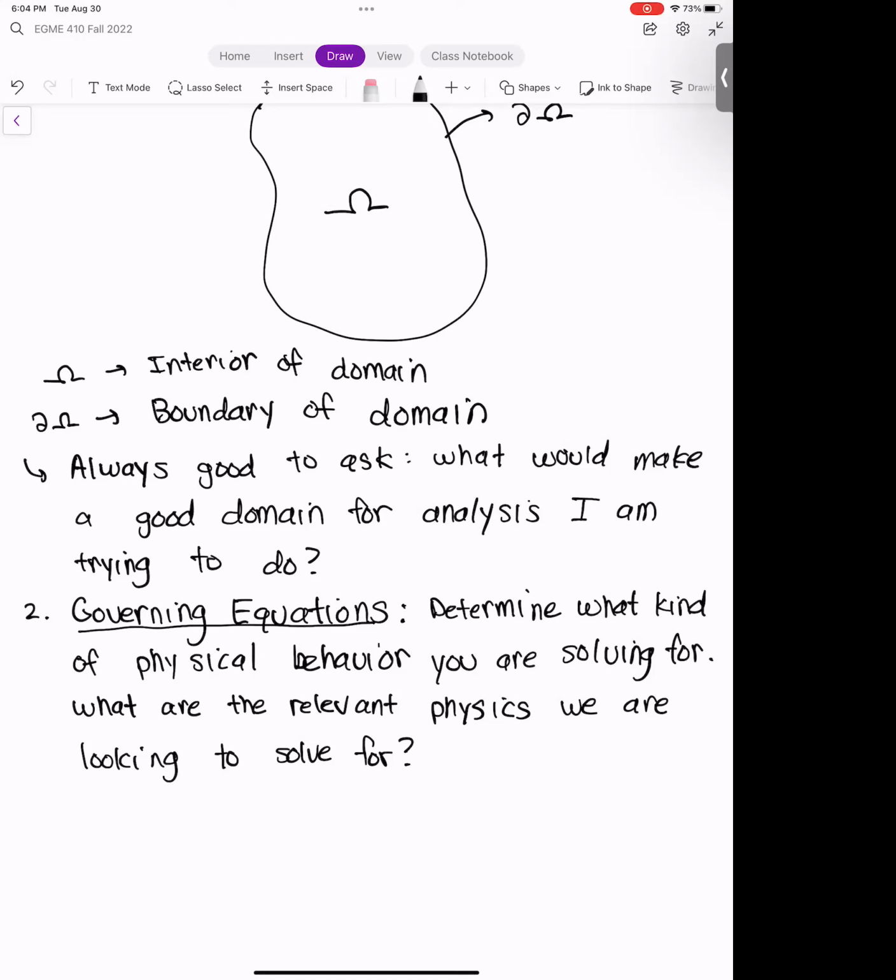And once you start diving deeper into finite elements, there's a lot of variations on this as well, all right? Even in the realm of something like a structural simulation, there's lots of different structural simulations that you can think of, right? And so you have to think about what kind of material model you are going to use, right? Are you going to have a linear elastic material, or are you going to have some kind of composite material that has nonlinear behavior, right? There are lots of important questions to ask, and these are important because you want to make sure that you get the most accurate results possible. Okay?